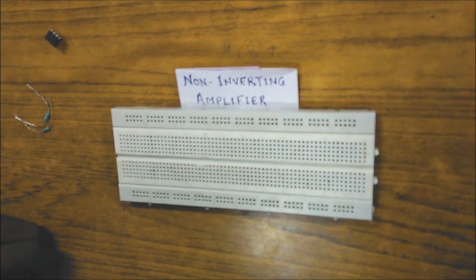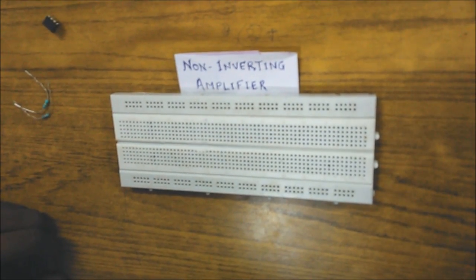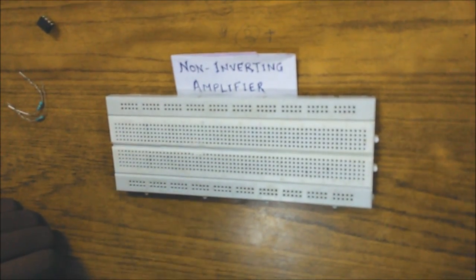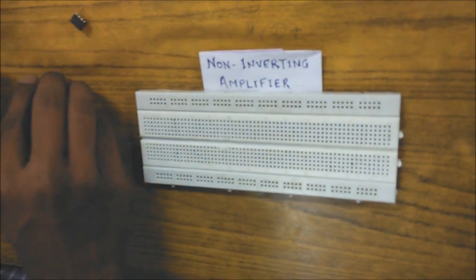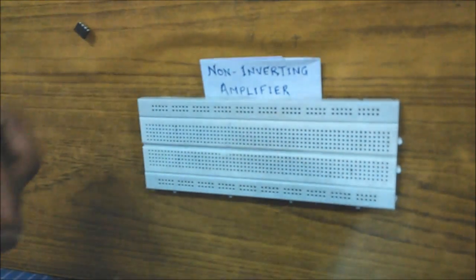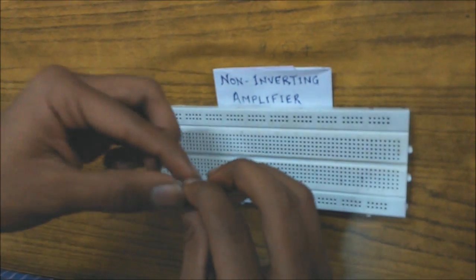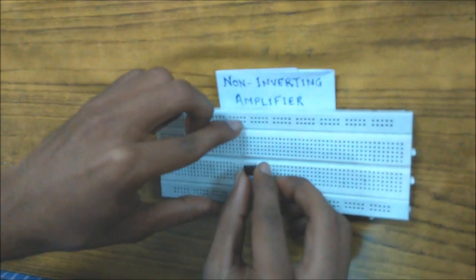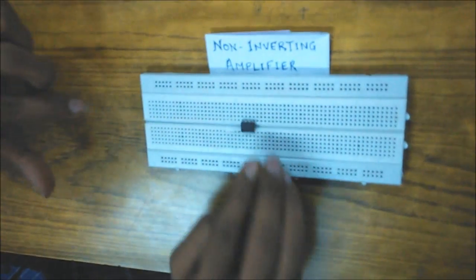To start with, the first thing is the breadboard you see right there on the desk. To do this analysis, you need to have two resistors and an op-amp IC, which is 741. Now we'll insert the op-amp IC into the breadboard and fix it in.